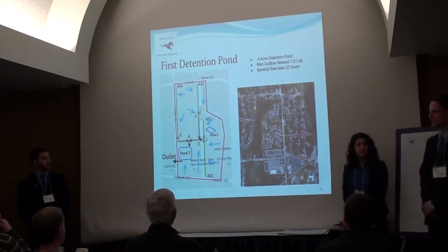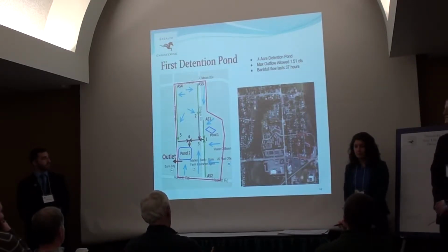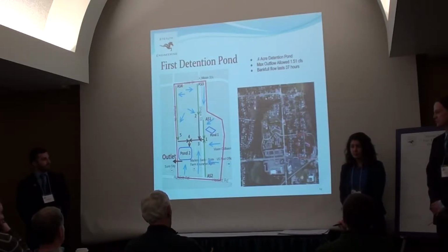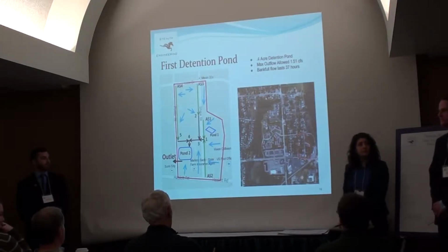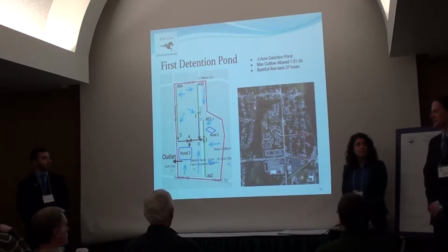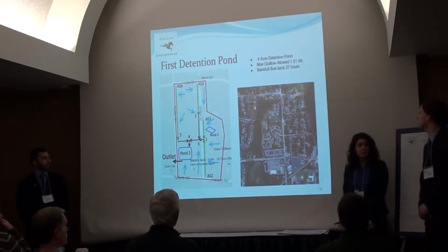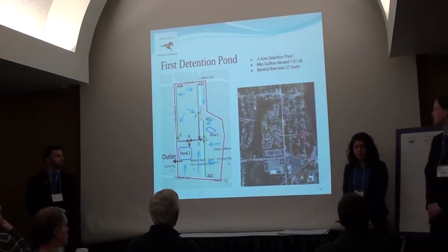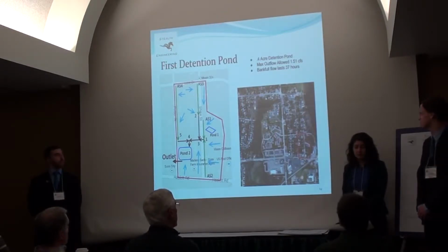This detention pond is 0.4 acres in size, and with the 10 acres of land running into this detention pond, with the regulations, it would allow 1.51 cubic feet per second because of the regulation that states that area times 0.15 is the pre-development discharge. So it meets regulations for the outflow rates during a 100-year storm. It also meets regulations when running the pulse method for the bankful flood values, as it takes 37 hours for the outflow to stop. So this also meets regulations.